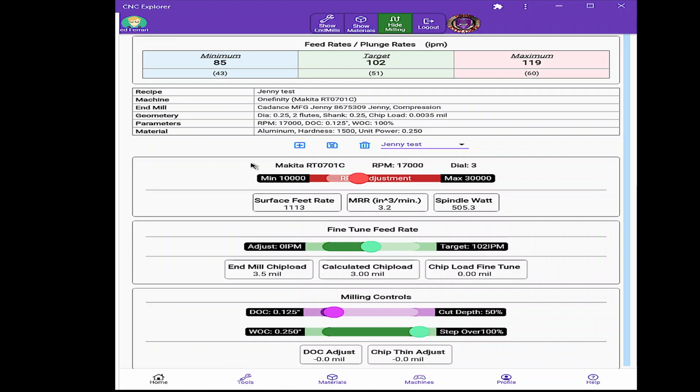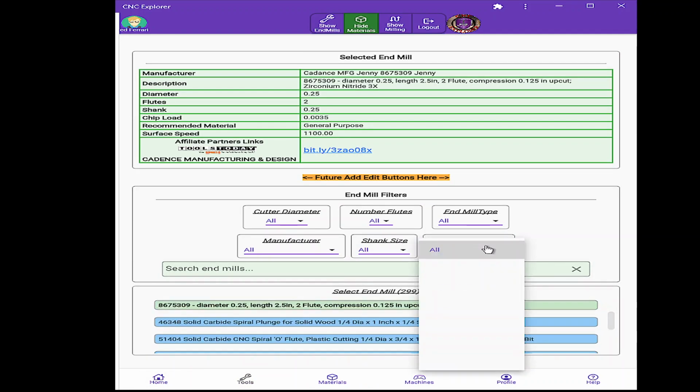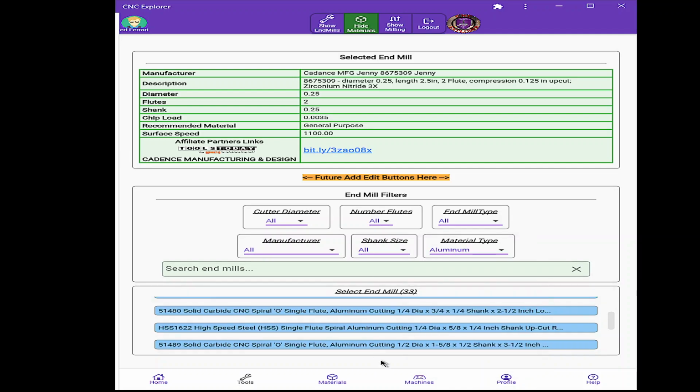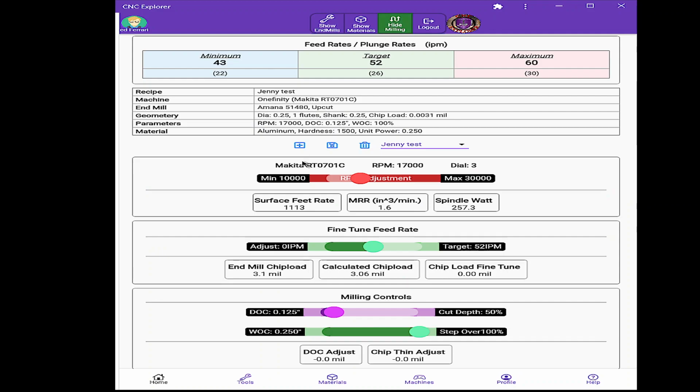So we're better off if we pick a tool that's designed to cut aluminum. So I can go over here and select for aluminum bit. Let's pick, this one's good enough. Single flute aluminum bit. Now my penalty is virtually not affected. The tool is designed to cut aluminum.